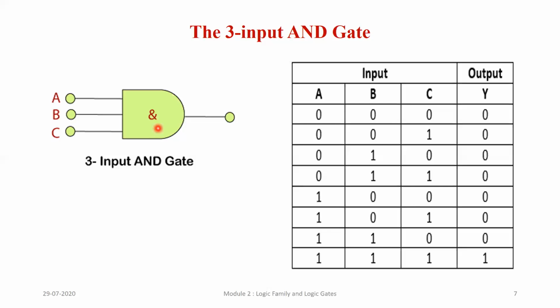Now, why do we go for CMOS? Because they are faster. When I give an input, there might be a little delay in getting the output. All those delay parameters are improved in the case of CMOS ICs. So we have the TTL family and the CMOS family. In the lab, whenever we are doing the practical, we will be using TTL gates. There is a series by which you identify the gates when you ask for them in the lab. You have to say, give me the 7401 IC, 7402. So that is the 74 series, the TTL series.